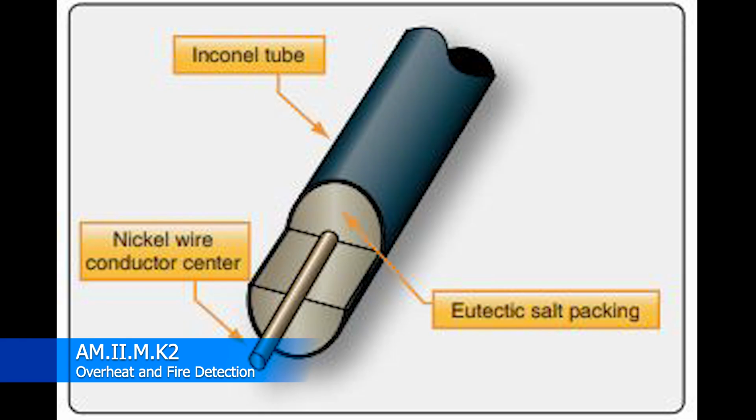and that's when you get your alarm. Now, what's cool about this is that, let's say you extinguish the fire. Once you extinguish the fire, the temperature is going to automatically start dropping, and that's going to allow the resistance to come back into the wire because the heat dropped off, and then it's going to extinguish the light. That's pretty neat. So you could be flying along, like, oh, we have an engine fire. We pull the fire handles, the bottle discharges, puts the fire out. Then all of a sudden the temperature starts to go down. It's like, oh, now we can see that the fire is out. And so then you can report that to ATC, since you've declared an emergency. Like, hey, look, the fire's out, but we're still coming in to land. Blah blah blah. And you can also know that you're not going to catch on fire any more than you already have.